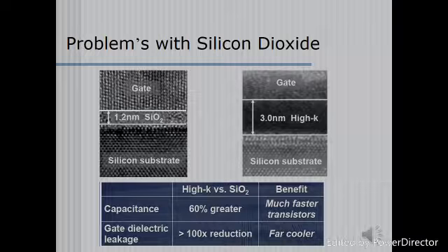When the thickness of the silicon dioxide reaches 1.2 nanometers, the leakage current density can reach up to 100 nanoamps per centimeter squared, which will break most devices when connected. If we go even smaller, the surface of the oxide will cause fluctuations to the characteristics of the device.